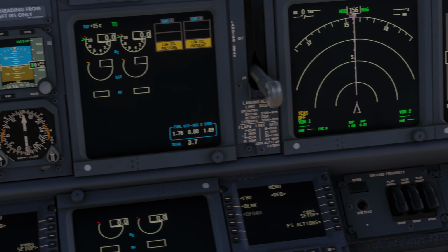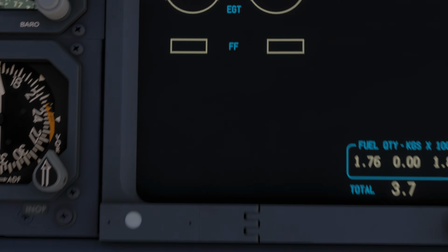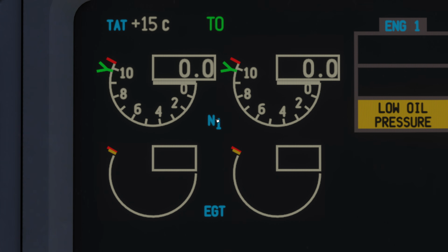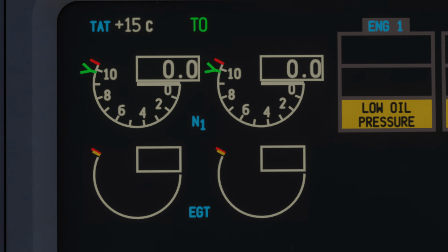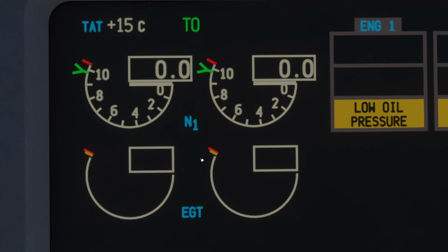Now, let's go ahead and get started, and rest assured this is exactly the same between Boeing and Airbus, so it's done on the example of the 737 here, but you can apply this knowledge to your Airbus as well. We're going to start from the top to the bottom over here. The top instrument is usually the one that's actually telling us how much thrust we produce. The majority of engine manufacturers choose to do this by the value of N1, while some others are going, for example, for EPR. We'll be talking about the differences in a few moments, but we are going to start with N1 over here.